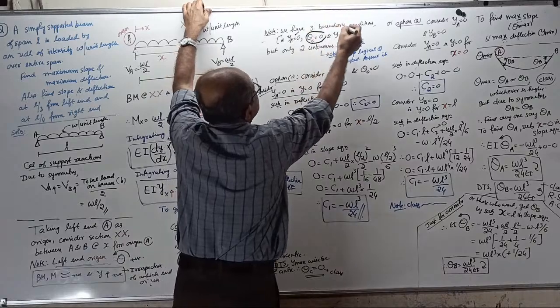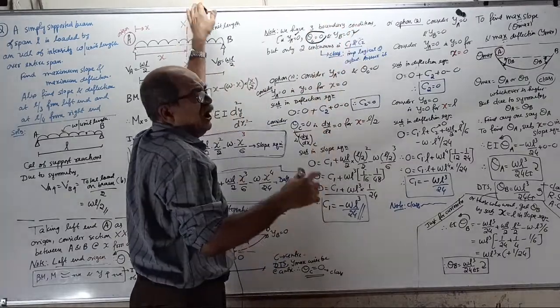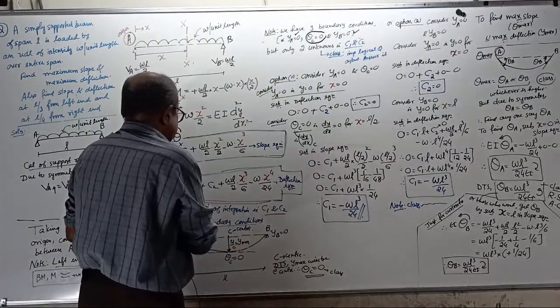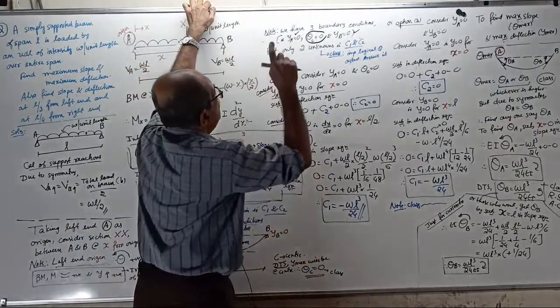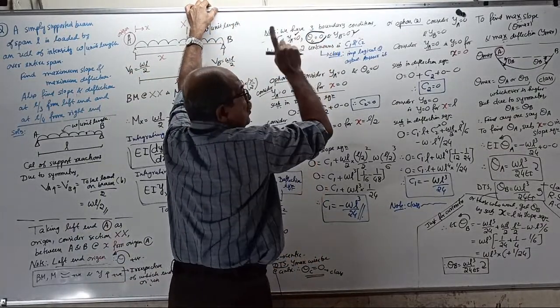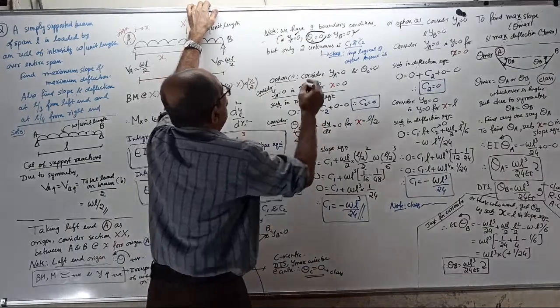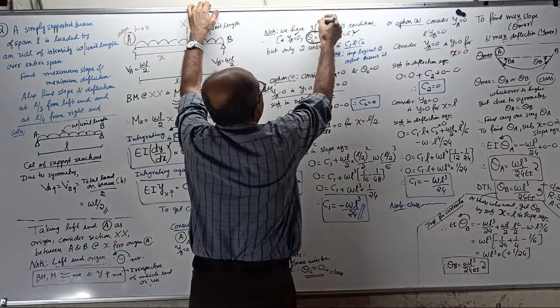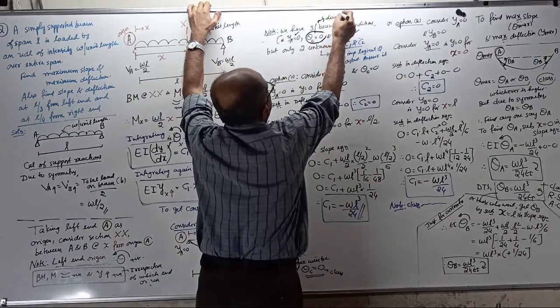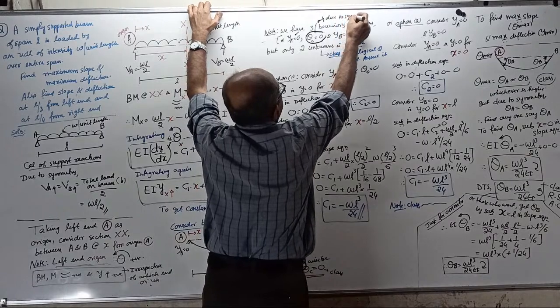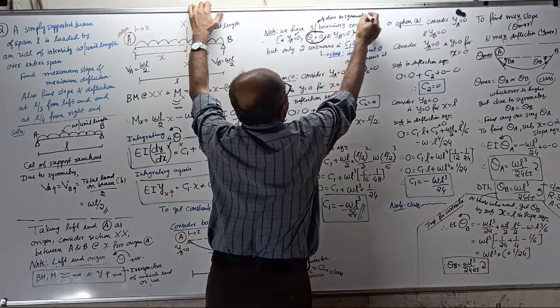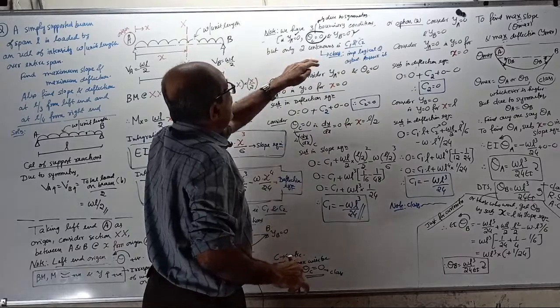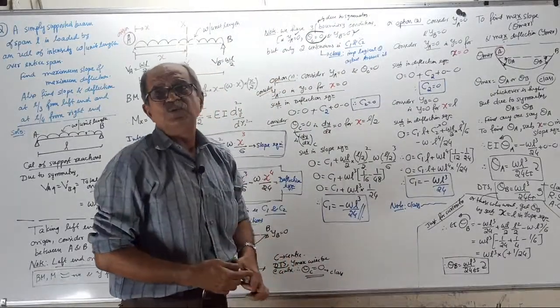These are always correct. Symmetry or not, deflection at A 0, deflection at B 0. Slope at center will be 0 only for symmetry. You can make a note here. See, this is only due to symmetry. Okay. Now, but only two unknowns, C1 and C2.